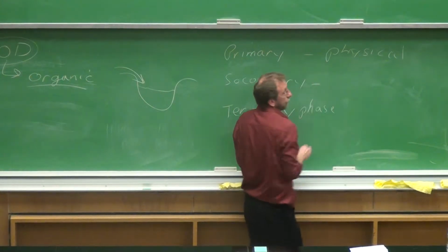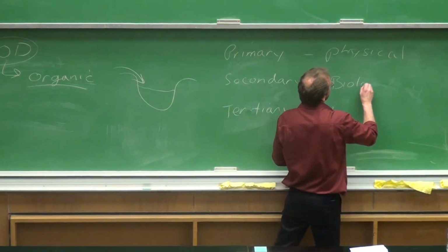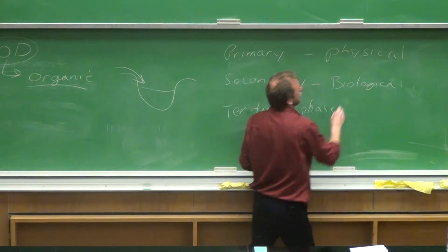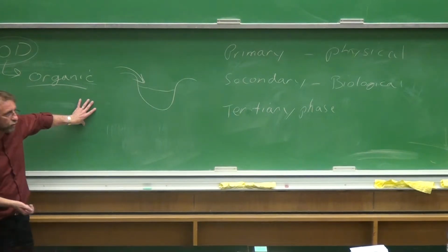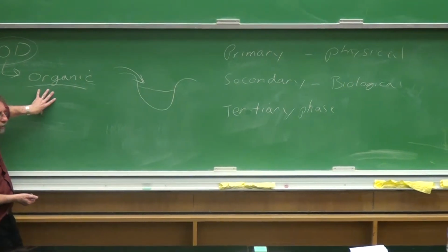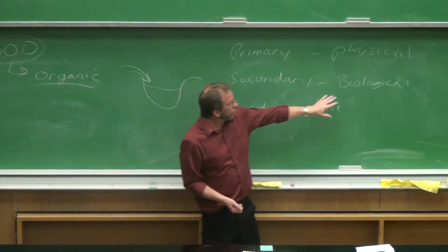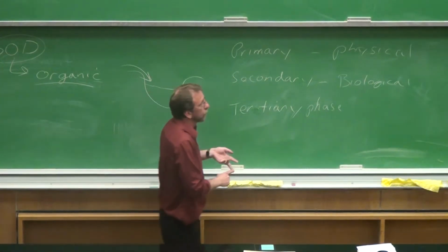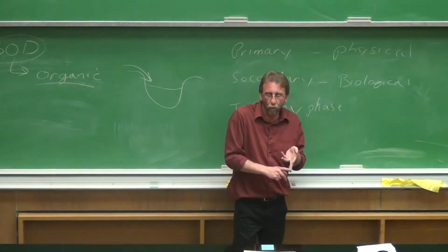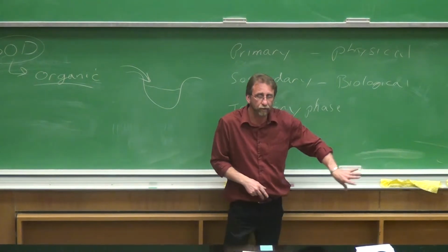And so our primary treatment is going to remove some of that organic matter. It's a physical process. Now our secondary treatment, if you remember, this is a biological process. It takes advantage of microbes and this breaking down of the organic matter that is in the water column. And it is how we remove BOD then. We talked about the trickling filter towers, we talked about the activated sludge tank, we talked about wetlands and lagoons that are used sometimes as a means of biological treatment.